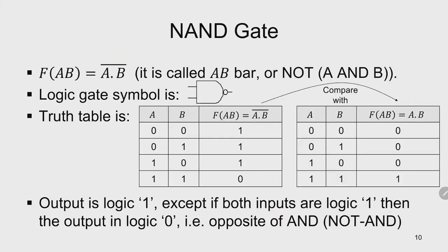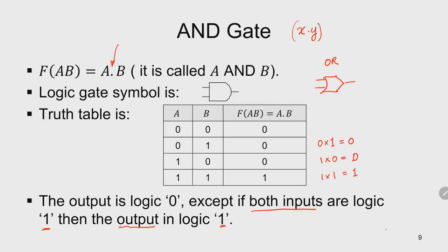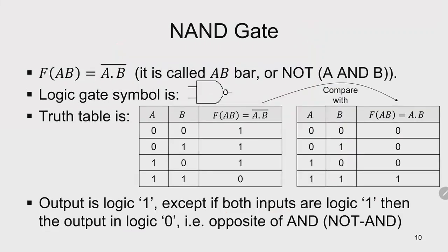So this is its variation, the NAND gate. In actual fact, you only need to remember the logic of an AND gate, which is the basic gate, and you should be able to derive the truth table of the NAND gate. NAND means not AND, or negate of the AND.